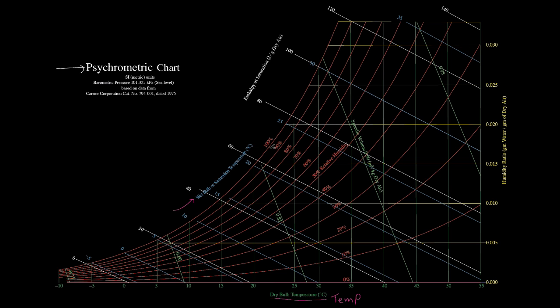Now on these red lines here, we have 100%, 90% marching all the way down to 10 and 0% humidity. This is the relative humidity of water in air. And so if we had a dry bulb temperature of 20 degrees and we were to go to 100% saturated, we would have the wet bulb temperature equal to 20 degrees, meaning we wouldn't have any evaporative cooling.